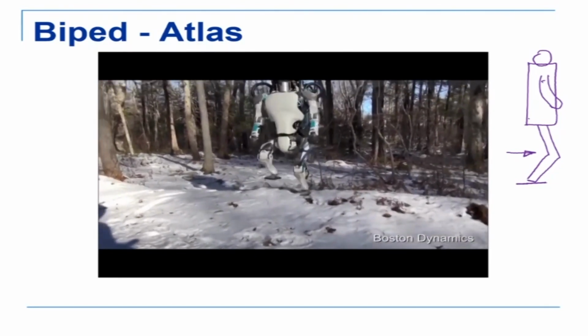Human beings walk straight. If I talk about a human being, our legs would be like this, straight, with no bend there. Whereas in the case of the robot, it is like this. That is essentially because for balance and stability, this kind of bent structure is more stable than this structure, because this otherwise behaves like an inverted pendulum. So it can fall very easily to this side or that side.